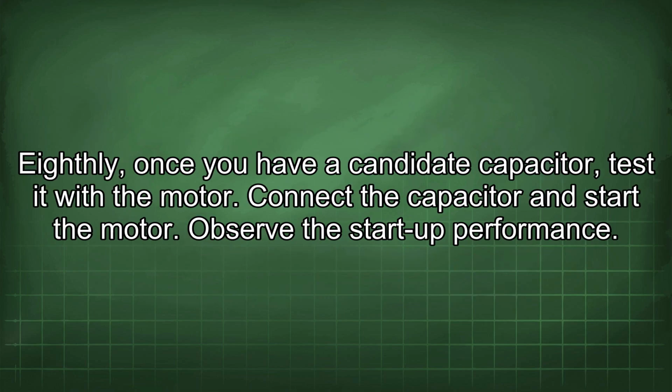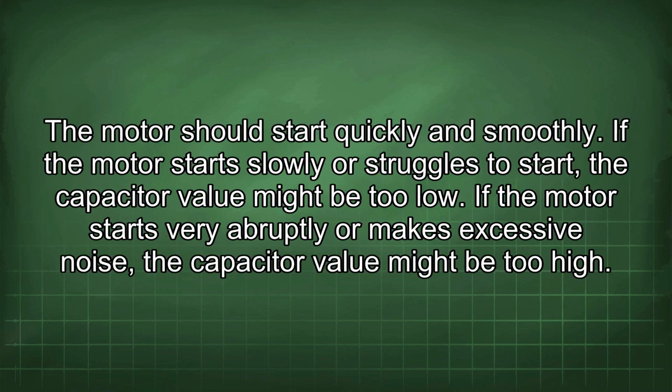Eighthly, once you have a candidate capacitor, test it with the motor. Connect the capacitor and start the motor. Observe the startup performance. The motor should start quickly and smoothly. If the motor starts slowly or struggles to start, the capacitor value might be too low. If the motor starts very abruptly or makes excessive noise, the capacitor value might be too high.